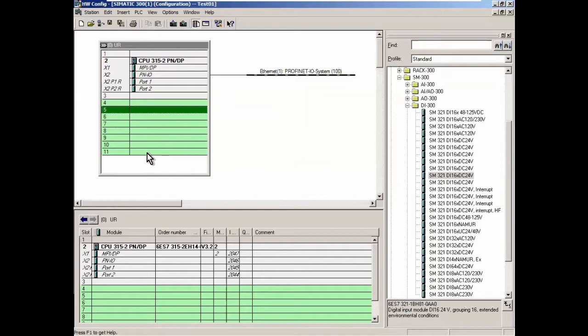The reason I would suggest you think like that is because when you go and look at the rack, you're not thinking, is it input 0.2 or is it input 55 point something? You want to know which slot it's on, which channel it's on. So we will develop an actual geographical addressing for this I/O.